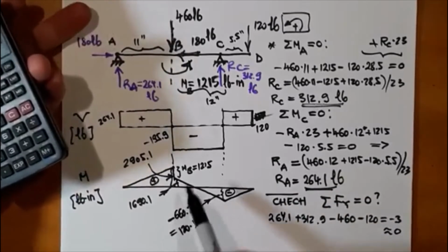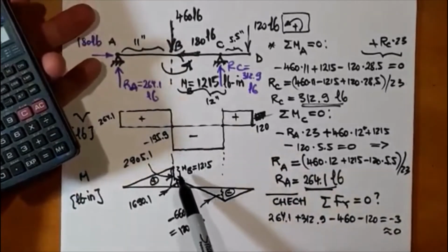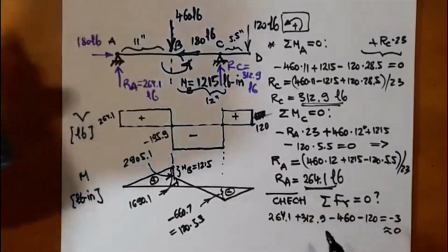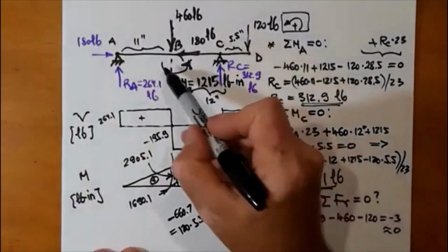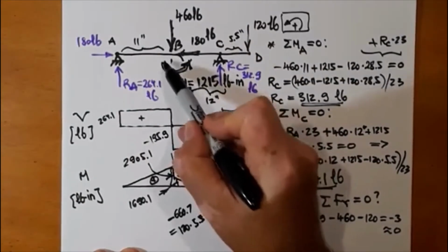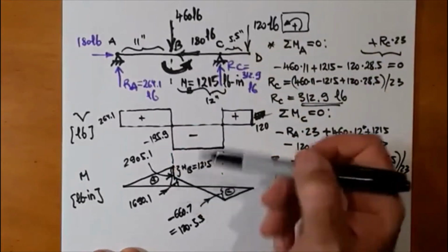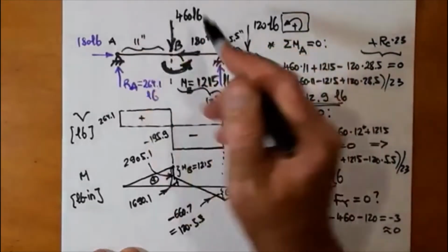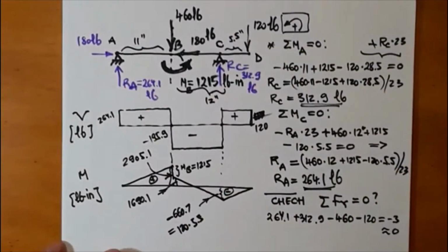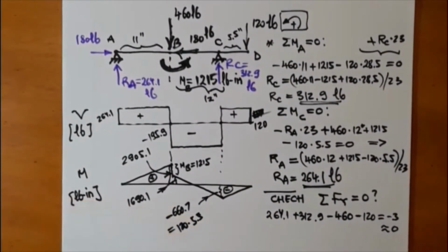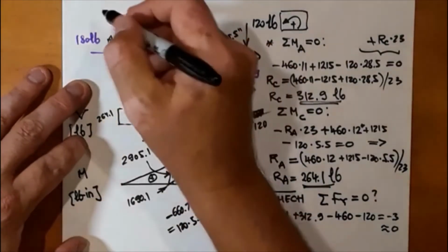All right, so we have the diagram. We have the maximum values of the moment. Remember the concentrated moment here. It's causing a drop, a reduction in the moment right where the moment is applied. And what I also did, in addition to what the problem stated to find these diagrams, I said let's assume the shaft diameter to be 1 inch.